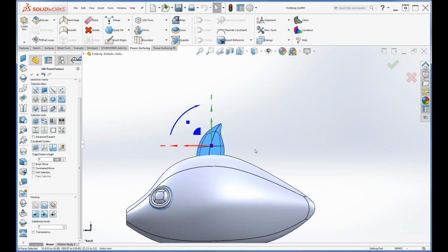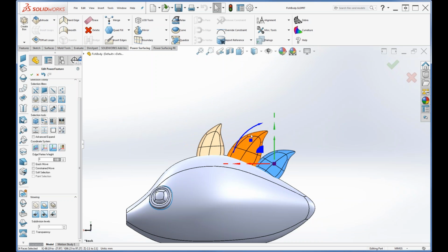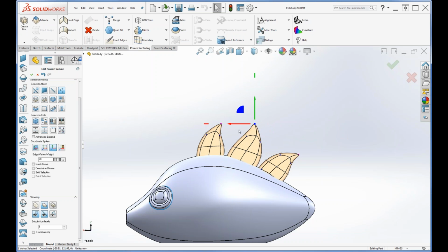Now, since we can deal with multiple separate objects in our sub-D edit mode, we can now clone them. So I'll clone this guy over here, take him over here, maybe I'll scale him up a little bit. And I'll go to this guy and do another clone. I'll bring it over here. That's kind of okay, and I can go ahead and edit them. Maybe I've decided that this one should point that way, and maybe this guy needs to be a little skinnier. So anyway, I've got 3 separate objects in here.